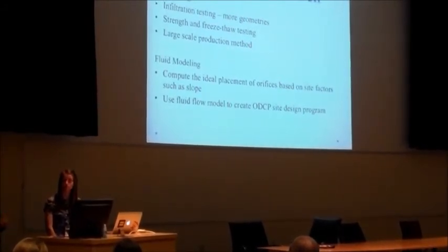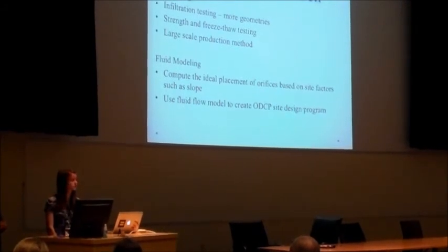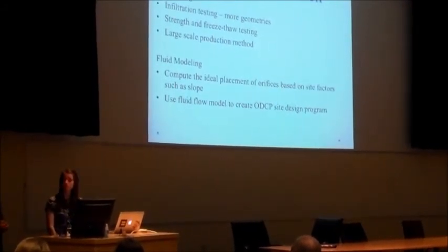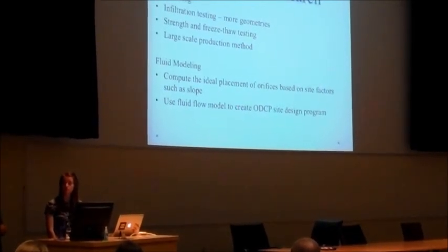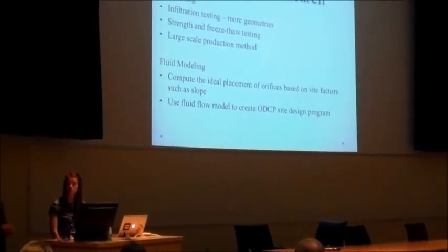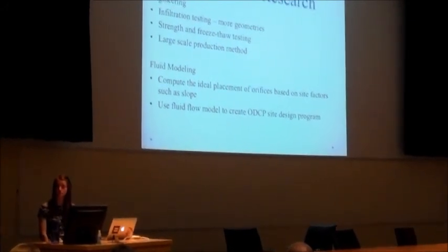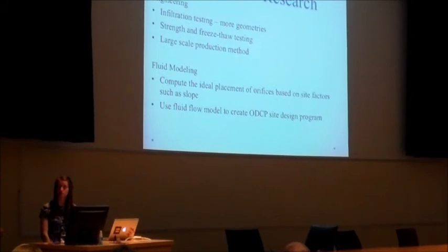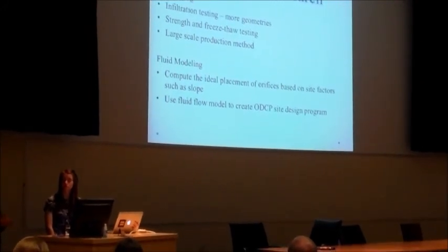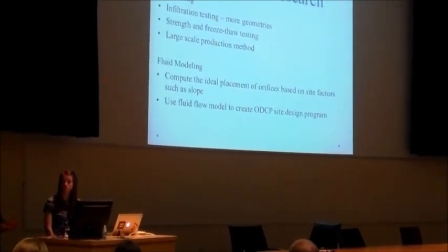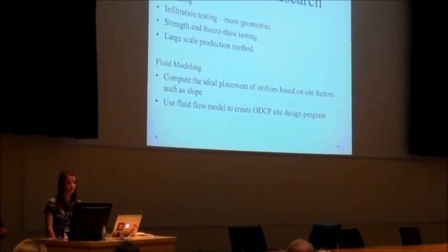The water freezes, when it freezes, it expands about 10% and pushing about 140,000 psi. So if this pavement is confined, if it's completely saturated, it's very likely that it can break apart and fail. And a failing would be parts of it chunking off, and it wouldn't be able to support any weight at all and would be very dangerous.